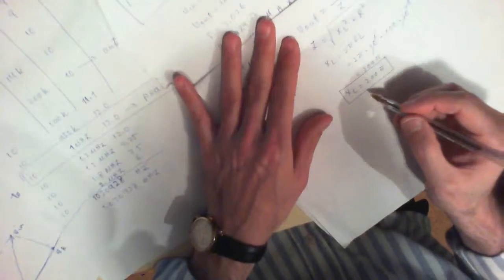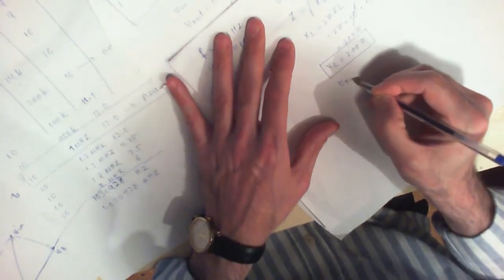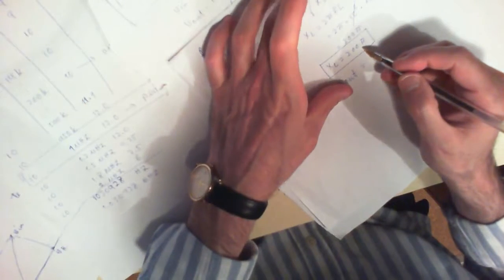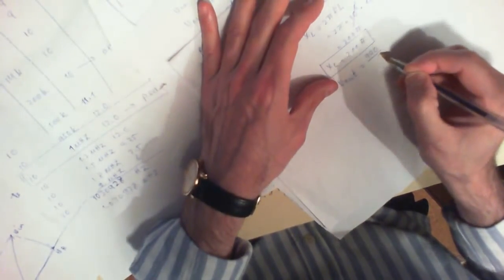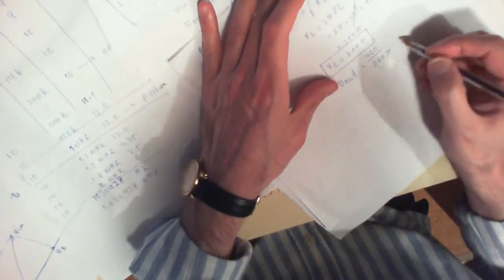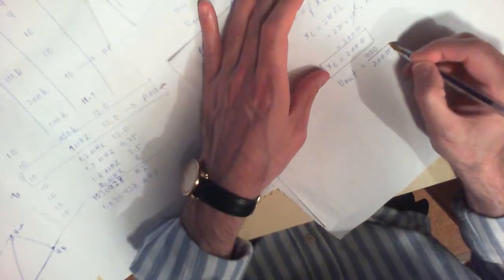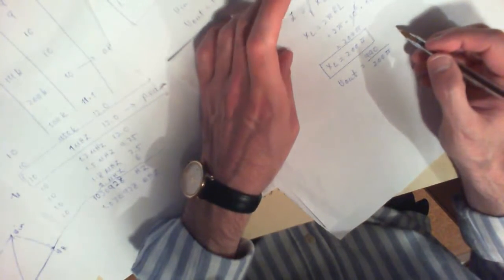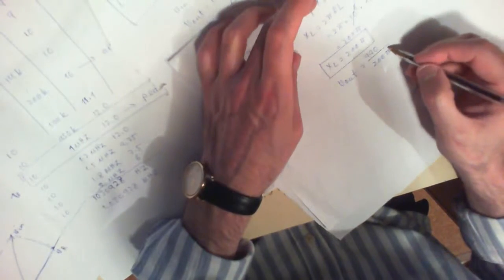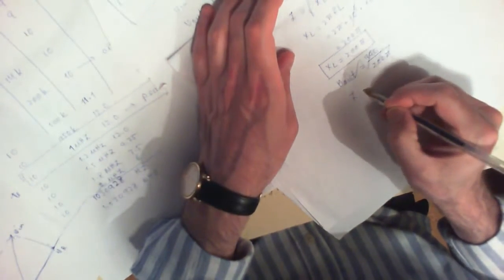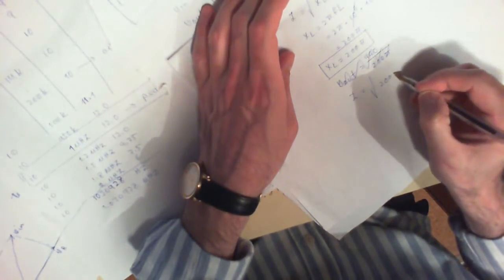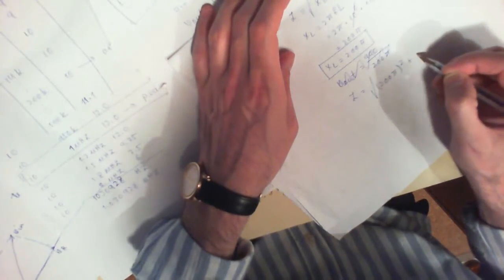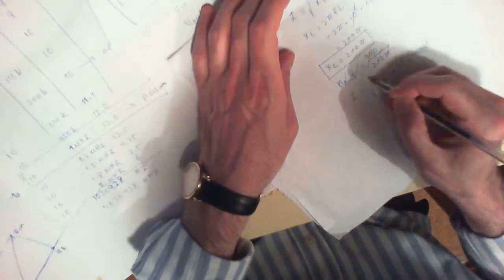So now V of out here is equal to R over Z, R was 990 ohm, 990 over 200 pi. Oh, sorry. No, I'm making a mistake here. Z is equal to the square root of X of L squared, which is 200 pi, whole squared, plus R squared, 990 squared.